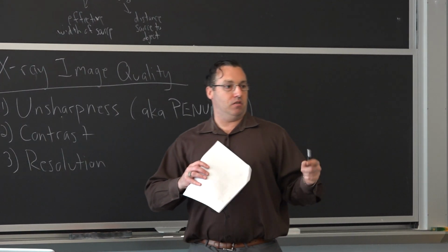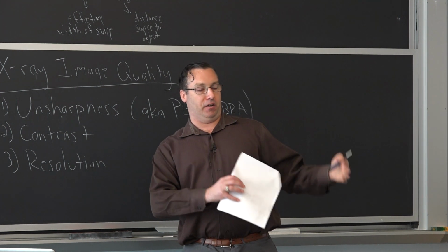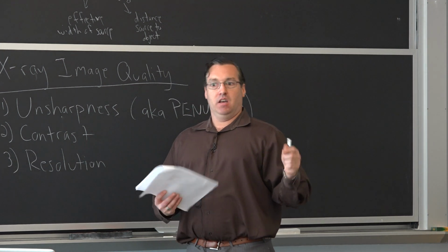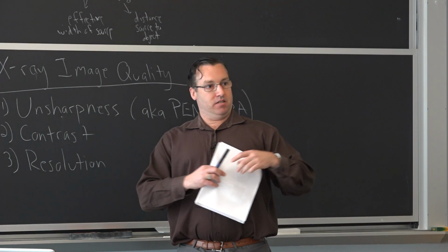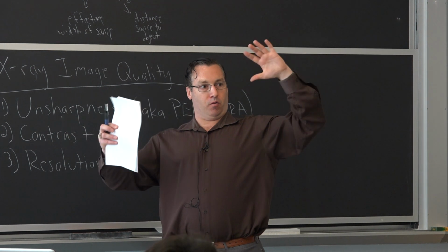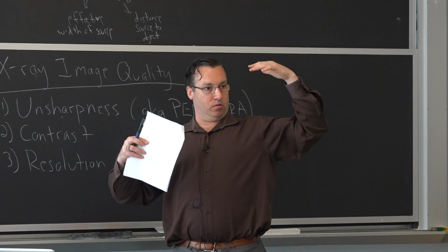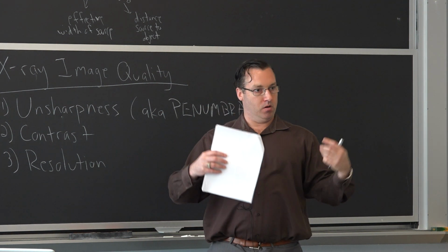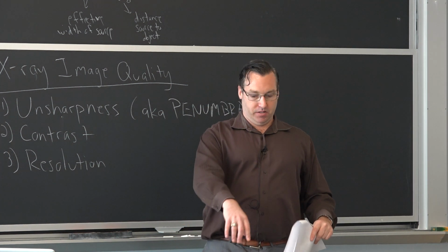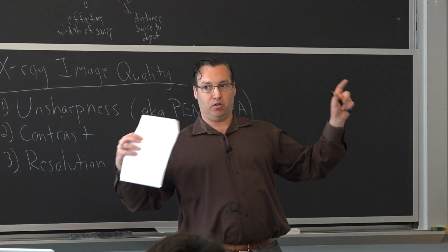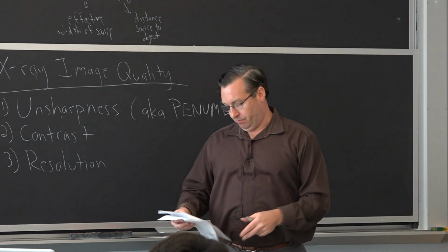It's the same thing, CT imaging in medical imagery, it's CAT scans. But the difference is, if a person goes in for a CAT scan, the X-ray sources move around the individual. For industrial CT scans of structural components, the structural component moves 360 degrees, and the source and the target stay stationary.